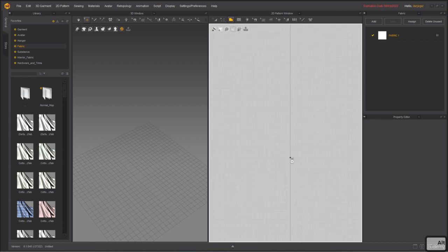Now, in the polygon tool here, there's one more thing that's very, very important. Actually, this is going to be the first exercise for this video. In this one, you can just add points, but patterns are usually not super harsh. Sometimes you're going to have some nice curves. So how do you create a curve? By clicking and dragging. If you click and drag, you're going to create a curvature. You can also press Control and click and drag. That's another way to do it.